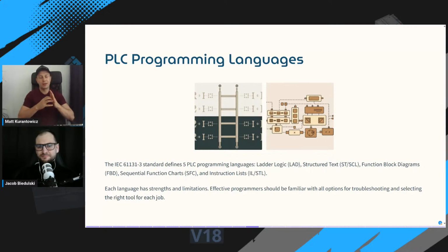Next, we have a text-based language, which is structured text. For all PLCs from different manufacturers, it is ST, structured text, and specifically for Siemens, it is the SCL language, but it's similar. They are similar to Pascal, and you find structures like if conditions or loops.